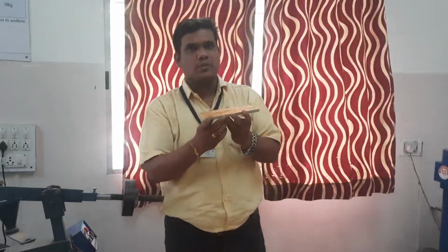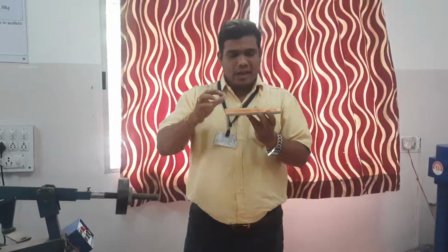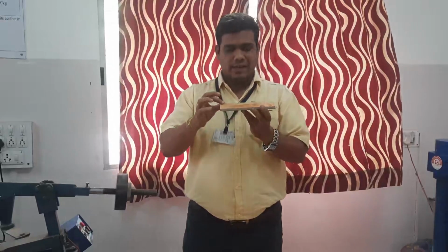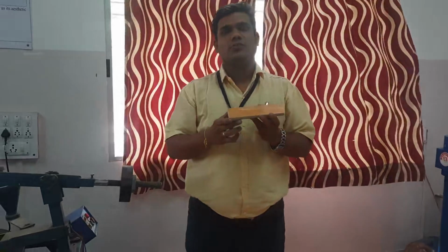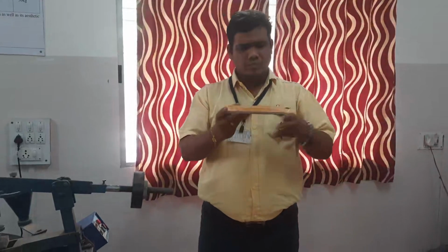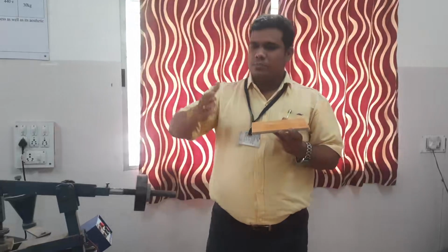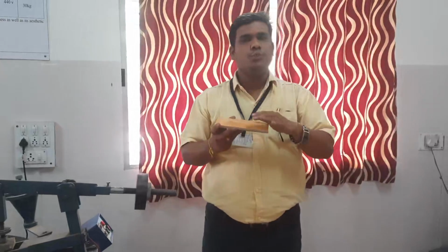For this purpose, when we select tiles for particular surfaces or purposes, the Indian Standard says that we have to go with a particular type of abrasion resistance. Whether it is cementitious tile, vitrified tiles, ceramic tiles, a paving block or a railway platform, depending upon the purpose the abrasion resistance should be different.